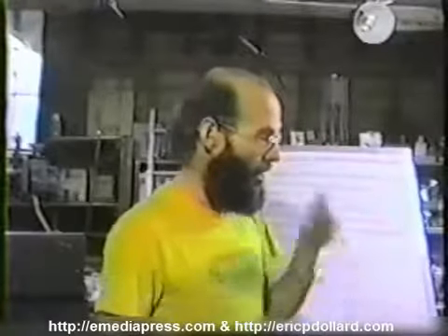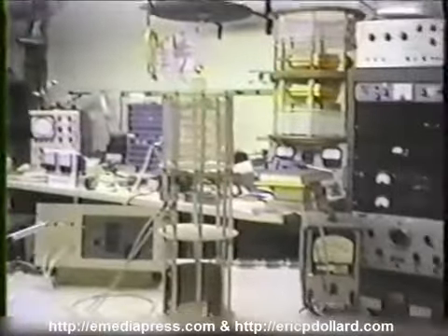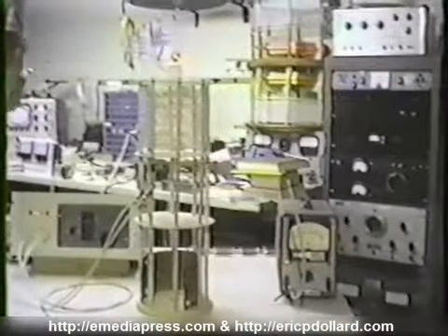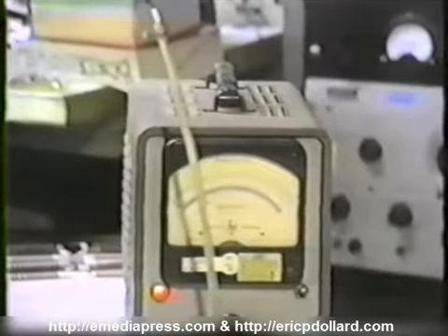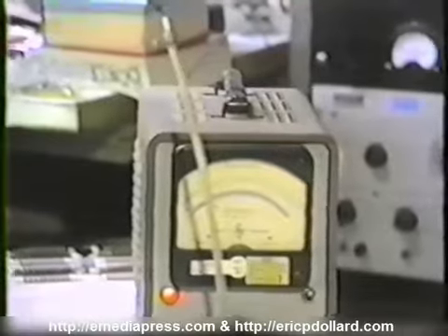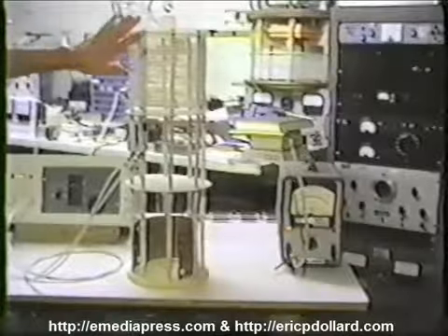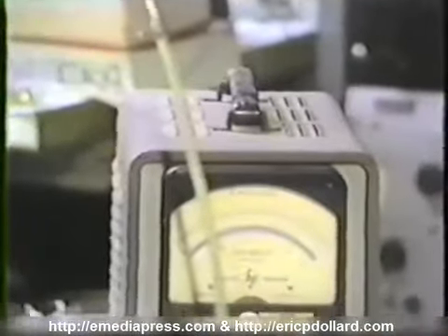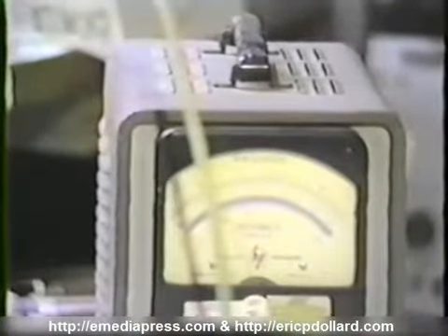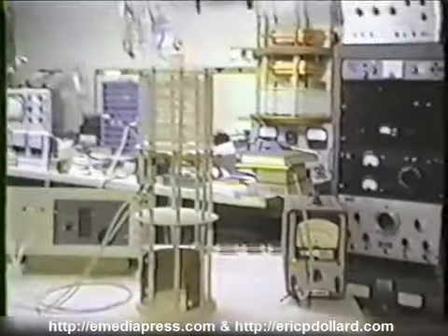to make measurements. In this case, focusing in on the voltmeter, when we use the longitudinal resonance structure, the thing is very sensitive, as you can see on the voltmeter, to any type of changes around it. So if you try to get in there to measure it, you can see by me bringing my hand near the coil that a definite shift out of resonance occurs in the meter. And as an example, I'll keep my hand very close to the coil and find the new resonance peak, and it's gone down about 30 kilocycles just by bringing my hand within 3 inches of the coil. And of course, I bring it away, I have to rehunt for the new resonant frequency.